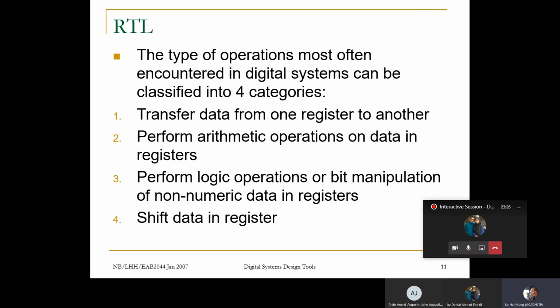And this is one of the hiccups that new designers always meet. The rule of thumb is to always use bitwise operations for hardware design. Always use bitwise and try to avoid logical operations, right?